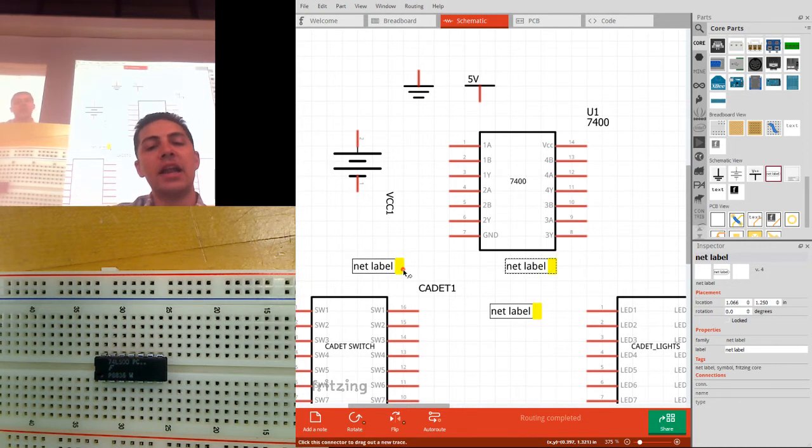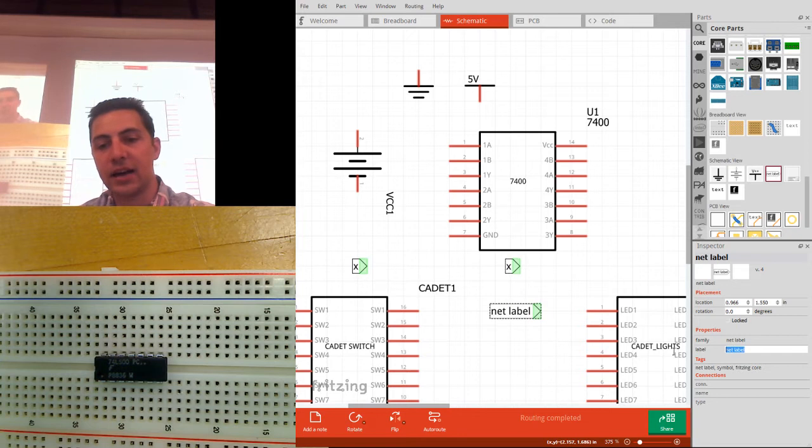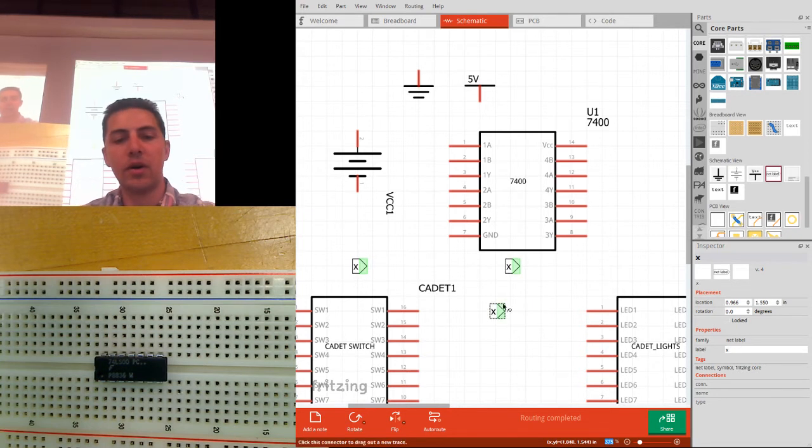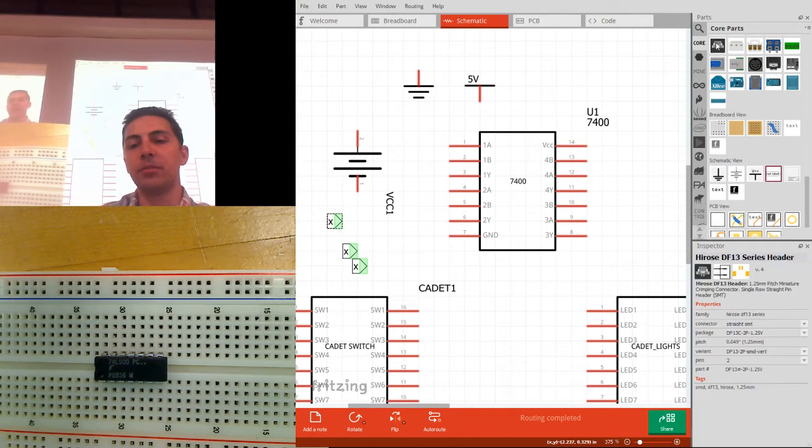When I click on a net label, all of the net labels that have the same name show up as connected. So I'm going to call this guy X, because that's the name of one of my inputs. Call this guy X. Call this guy X. Okay. And I'm going to need a few of these, because every place I want to use X, I'm going to put one of these net labels.